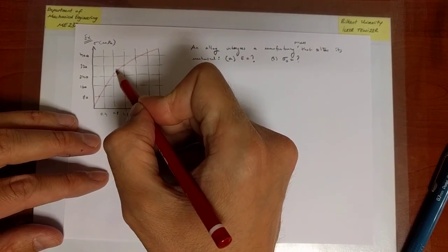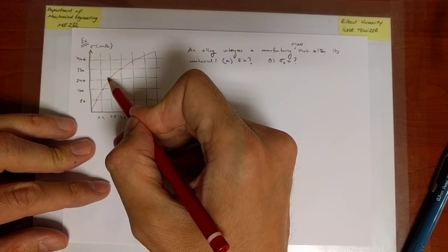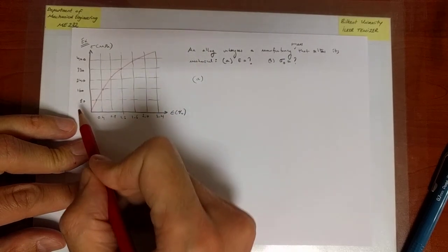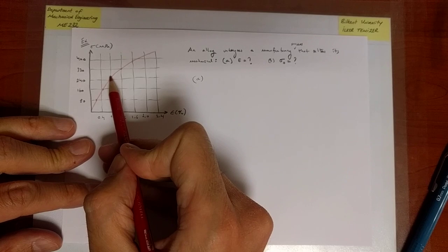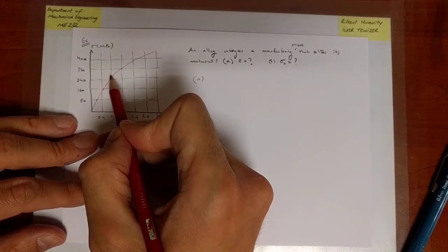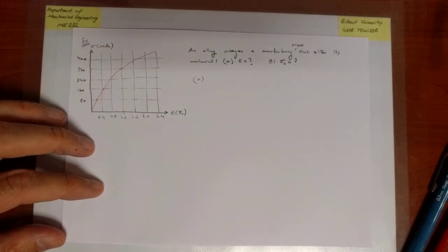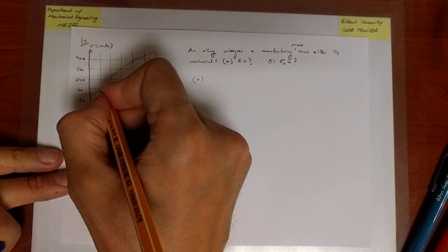So I don't quite have a distinct yield point. I certainly could have used the Ramberg-Osgood model, but I will eventually use elastic power hardening. But I can see that in that region probably the curve is almost flat, and I can pick 2 points.